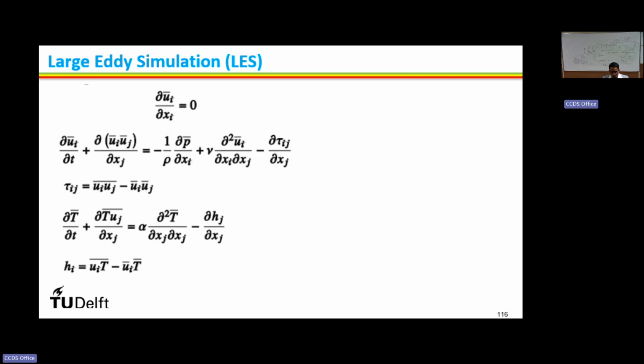So, the only way to find a mesh independent solution is to run on that mesh, run on a finer mesh, and compare the results. There is no alternate way. So, any more questions on LES? If no question, then we come to the end of this session.